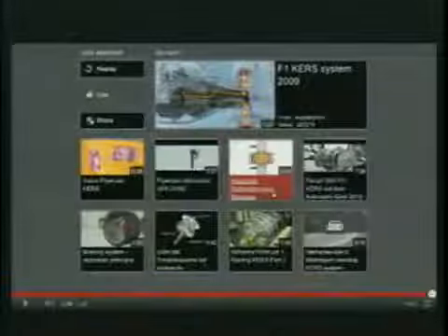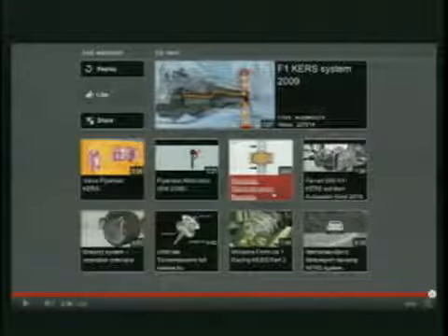Okay, so Volvo is at least contemplating producing these flywheels. As you see, as the car is coming to a stop, the flywheel engages and it basically picks up the kinetic energy that the car is losing and stores it, and then when the car wants to accelerate, it pulls the energy first out of the flywheel and moves it back up, and then the engine would kick on. So this is how hybrids work: they have a small storage capacity, and all that really needs to store is just that transient energy that you pick back up from stopping the car.